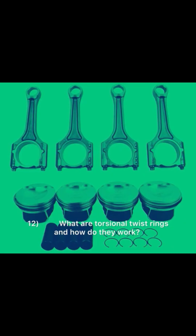12. What are torsional twist rings and how do they work? Have a bevel that is acted on by combustion gases. Twist up to seal against combustion. Twist down to seal and scrape oil. 13. How are piston rings indexed? Marking on one face of the ring to locate the up position. Note ring type in each position. Align gaps as per instructions.